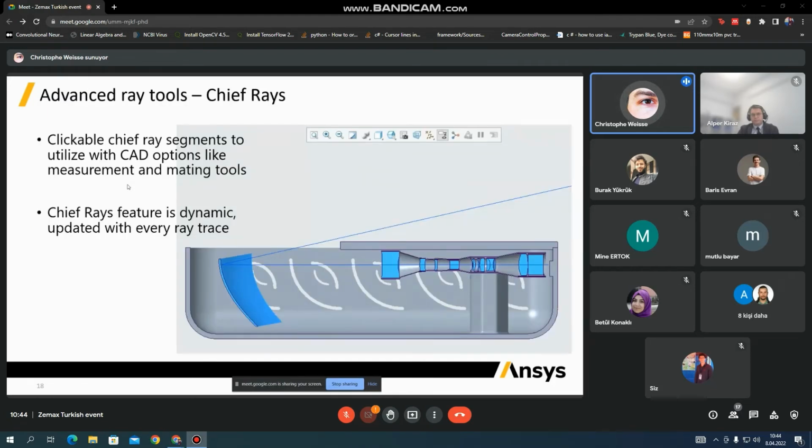I told you about the prepare for Optics Builder update tool in Optics Studio, basically to properly define a pupil that allows us to trace the chief ray directly in Optics Builder, so that you can have a reference, especially for systems that are using mirrors or any kind of off-axis or non-symmetrical system.